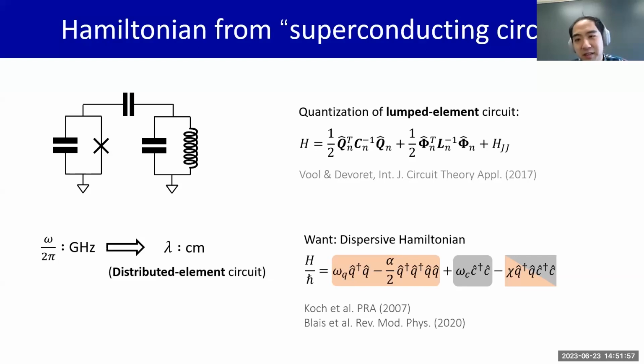So sometimes it's possible to actually design the circuit in this way, especially when you're doing 2D and most of the stuff being quasi-lumped elements. And that's the point, you can start everything in SC qubits, which is you parameterize the circuit by giving it L and C values. But in the 3D transmon experiment that I do, for example, I don't have an exact LC model for my whole package. So mostly I don't use SC qubits a lot in my design. I kind of just start from HFSS directly.